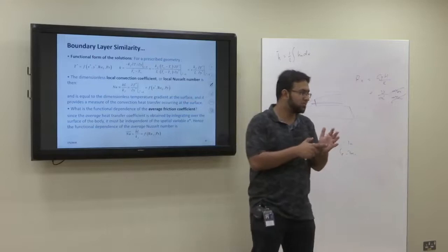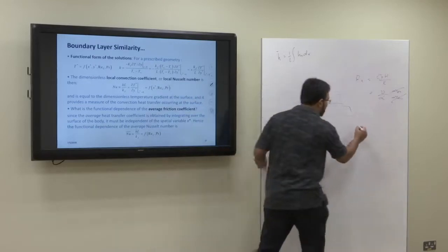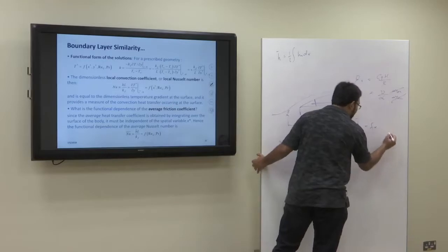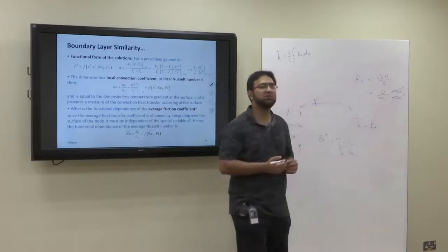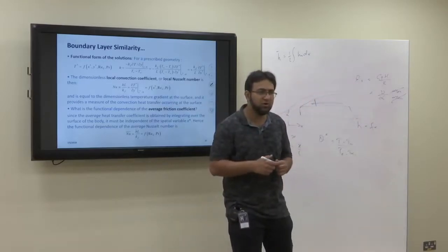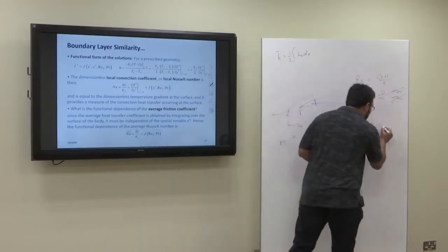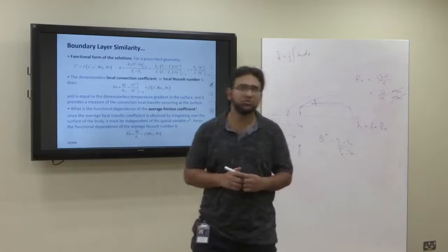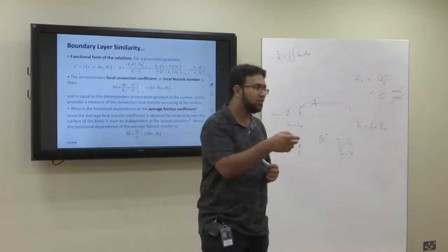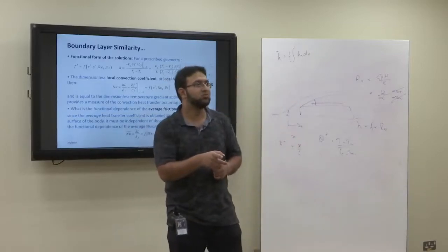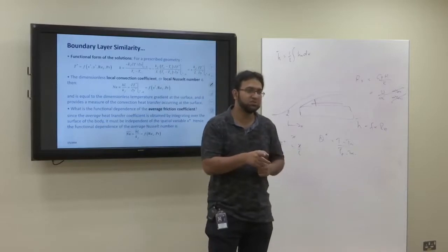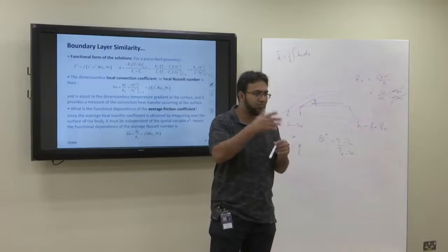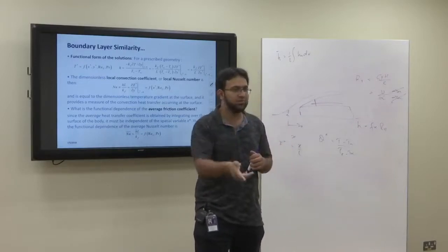So that means our heat transfer coefficient is a function of, how do we determine if the flow is laminar or turbulent? Reynolds number. So it's a function of Reynolds number, right? You change the Reynolds number, the heat transfer coefficient would change. The other thing, there was another parameter based on which the formula was changing, and that was the temperature. So we had different formulas, but within the formulas it was dependent upon temperature.